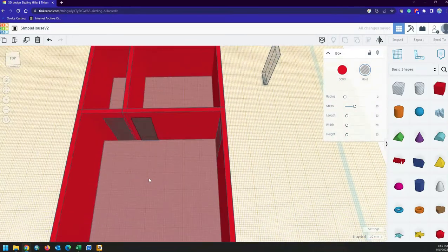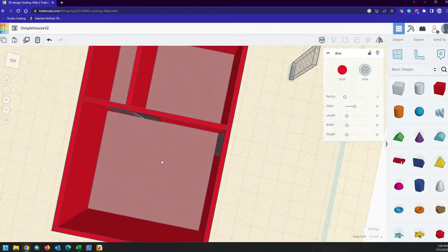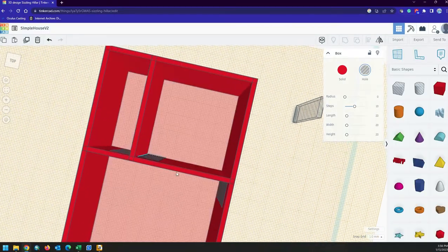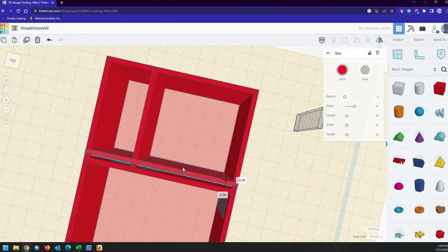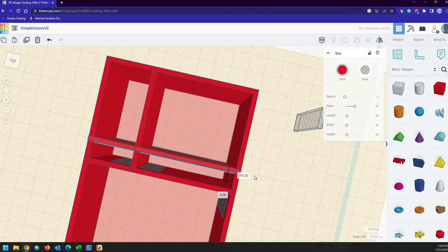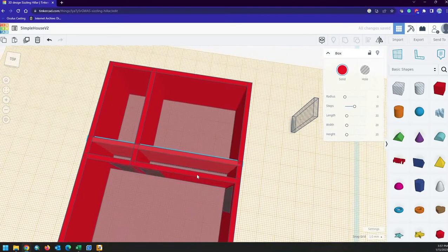Okay. And then we do need a closet here real quickly. So that's what we got to build a couple walls for that. So for the closet, we like to be 24 inches deep. So I'm going to go Control D from this wall, and I'm going to pull it out. We'll say negative 24. Oh, 24 is 2 feet is 8, I think. Negative 8. There we go. All right, that seems a little more reasonable.